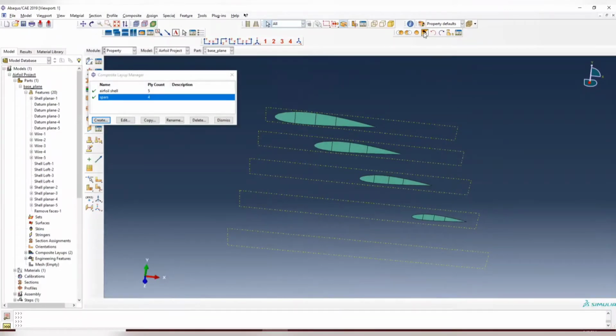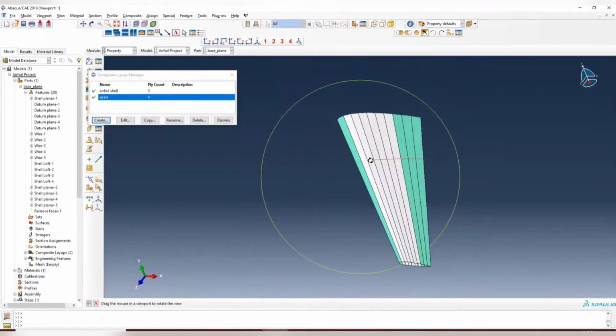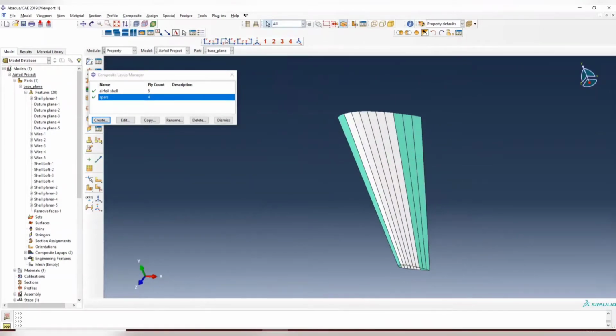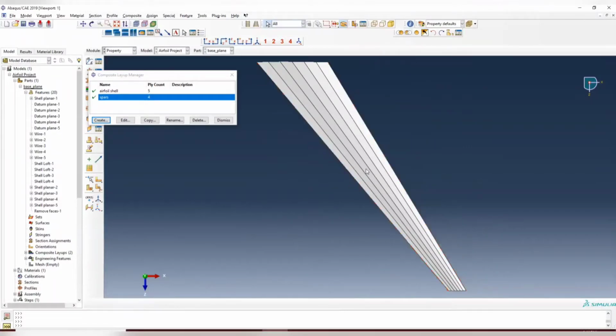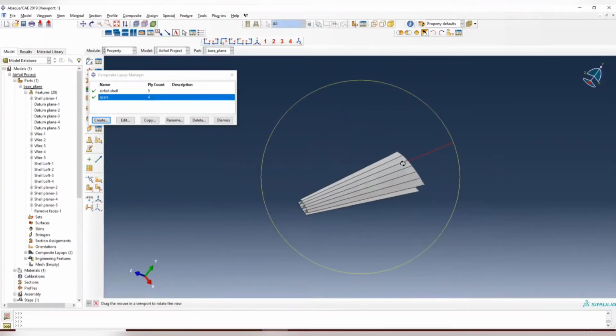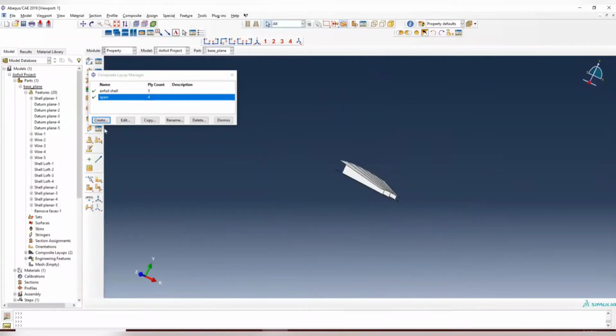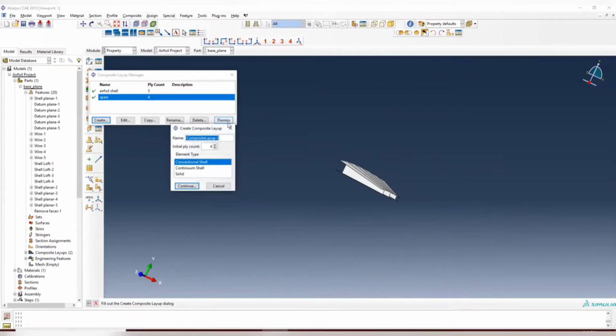And use this invert tool to get rid of all the sparse, leave only the shell. Now use XZ and then deselect, hold Shift and deselect everything that we don't need to assign material properties to. So the rest you can directly assign properties, call it stiffening shell.